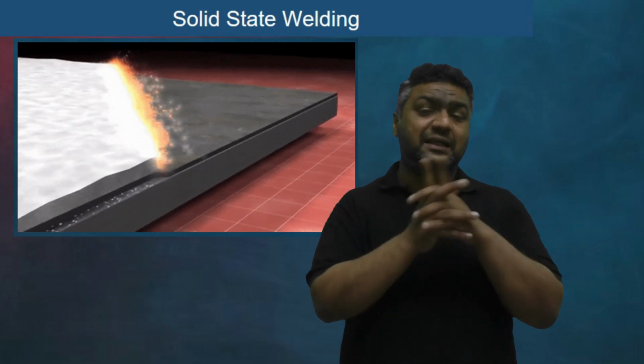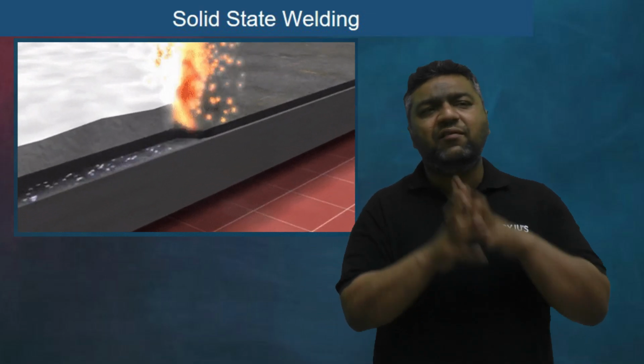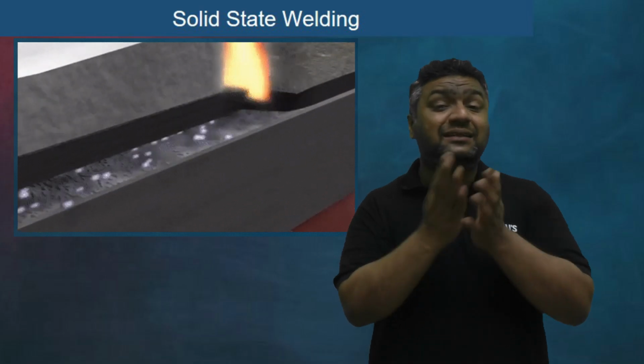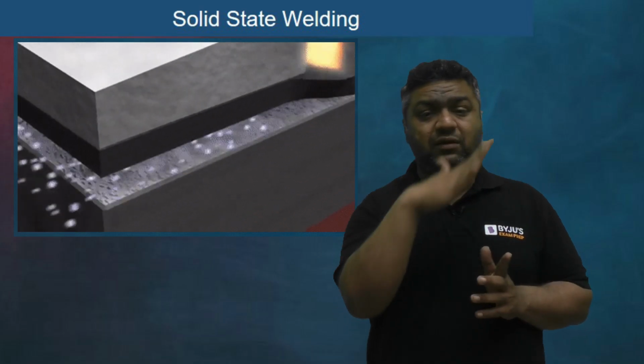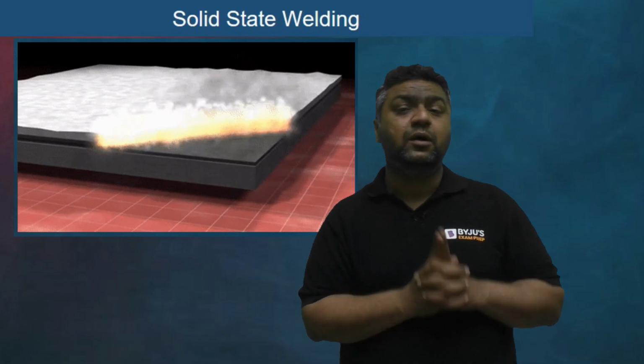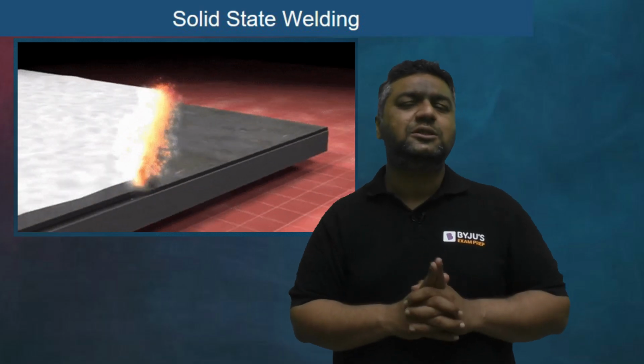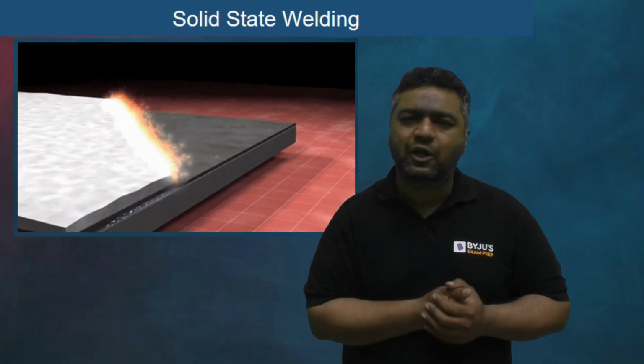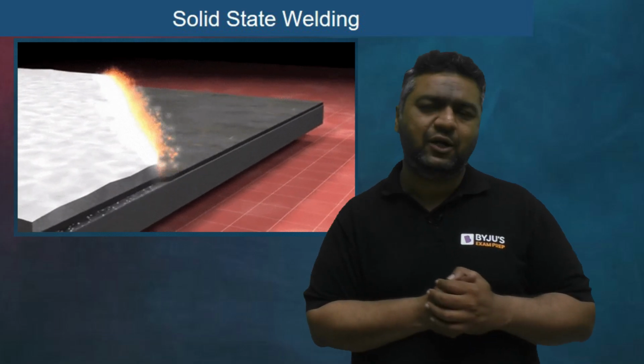Flyer plate is always thinner than the target plate, and whenever this explosion happens, flyer plate acts like a semi-solid, and just like it is flying and going towards the target plate and gets stuck over that. For the perfect welding setup, we are providing the standoff distance and also the angle. For cladding of cylinders, we are using this kind of process.